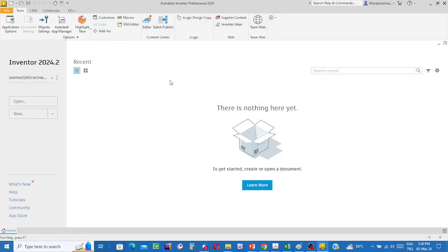Thanks to passing through such a stage, to repeat again, Inventor automatically finds that address at the file saving stage without asking the user. When I say open a file in the content of that work, Inventor automatically drops the list of the files that have been saved within the project folder. If it is so obvious, that can save time and effort. But the main value of the project definition is that, thanks to such a definition, the pack and go process will be applicable. Okay. Well, for design calculations, I said that, okay, why not?